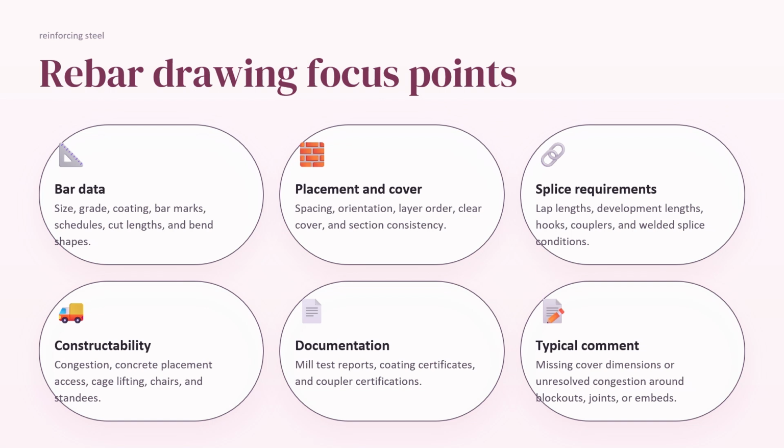Placement and cover. Spacing, orientation, layer order, clear cover, and section consistency. You need to make sure the spacing and the clear cover is matching. If not, check with the designers. Splice requirements, lap length, development lengths, hooks, couplers, and welded splice conditions.